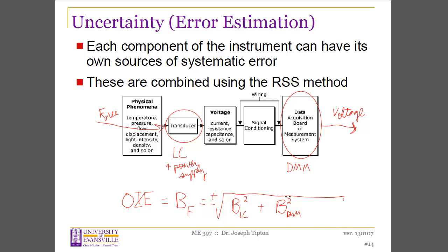We've got to remember, however, in the process that units might be different, and we need to use unit conversions using our sensitivities as necessary to make sure everything's in the proper units that we expect, forces. And when you come into lab on Thursday, we will put this into practice using a load cell and a digital multimeter to prepare you for your first big assignment.